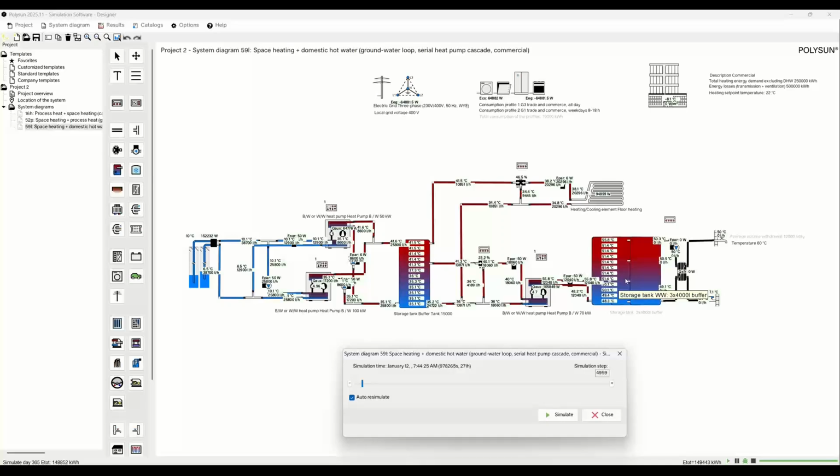So, of course, here we have a system that's split into several heat pumps. It has advantages over just using one, because if you just use one, you have one large component that needs to deliver to really different loads and different temperatures. So if you split that into several units, you can have one unit doing a special thing, running at its sweet spot. So it has a lot of advantages.